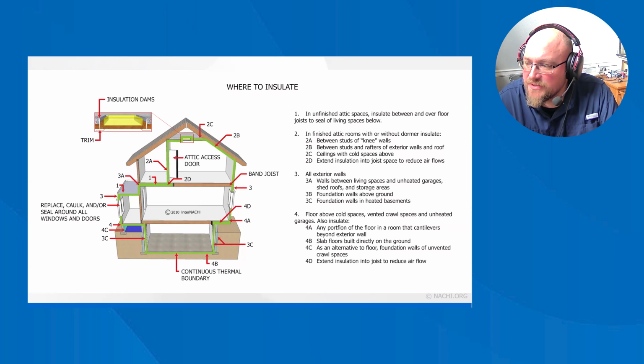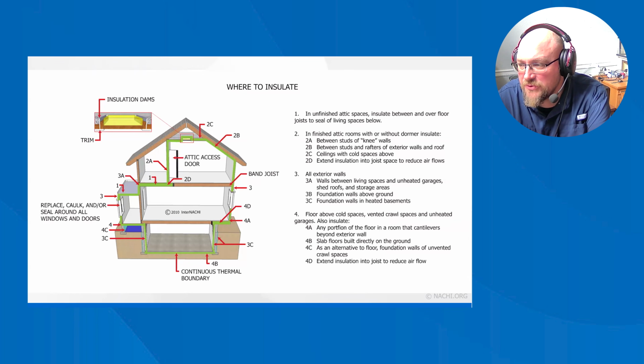Check the attics, walls, and floors adjacent to an unheated space, like a garage or a basement. The structural elements are usually exposed in these areas, which makes it easy to see what type of insulation is installed and to measure its depth or thickness. Inspect and measure the thickness of any visible insulation. If the crawl space isn't ventilated, it may have insulation in the perimeter wall. If the house is relatively new, it may have insulation outside the basement or foundation walls.